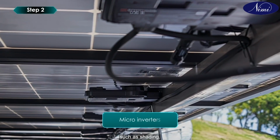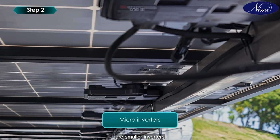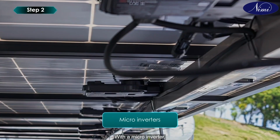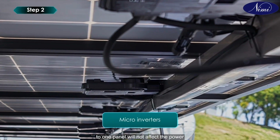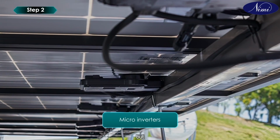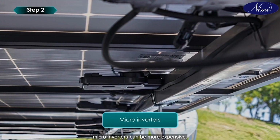shading. Microinverters are smaller inverters placed on every panel. With a microinverter, shading or damage to one panel will not affect the power that can be drawn from others, but microinverters can be more expensive.